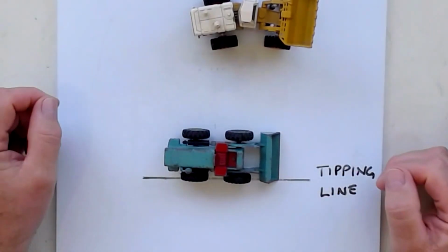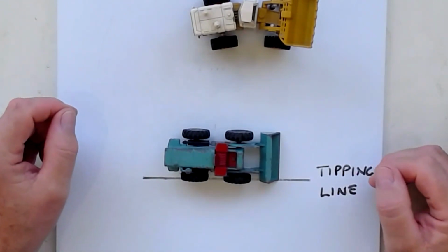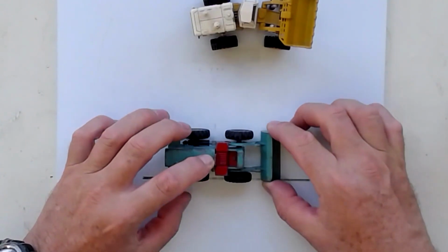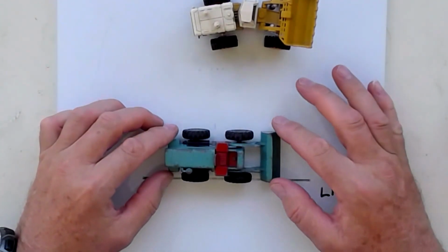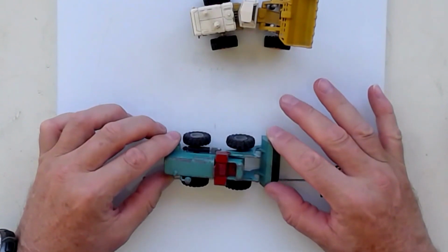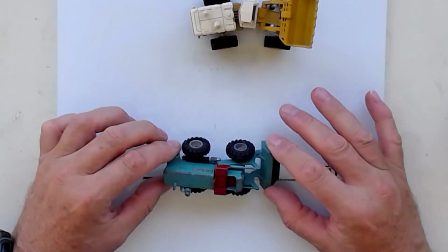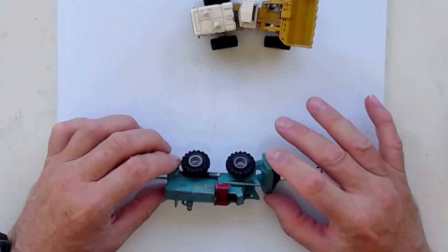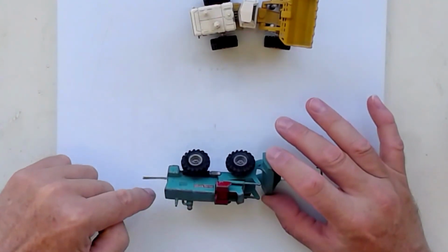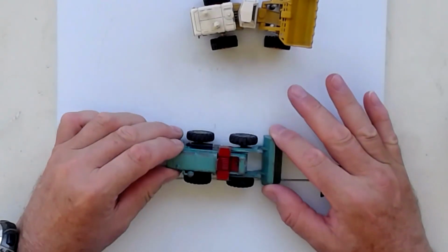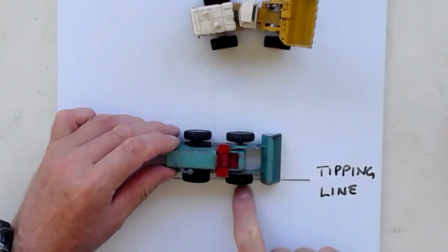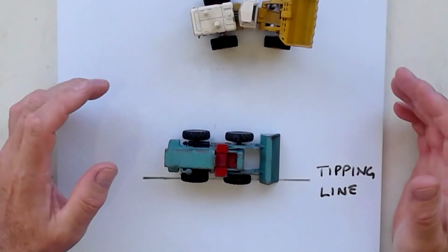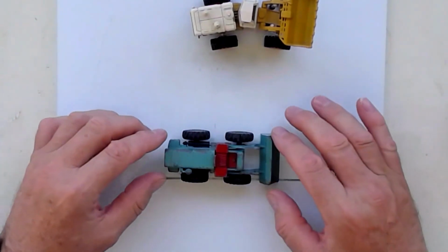When we look at a rigid frame vehicle, we can learn a few things. We talk about keeping the load close to the ground so that it can handle quite a lot of side slope before its center of gravity is on the wrong side of the tipping line. The tipping line is the outer edge of the tyre contact patch, the line about which it will roll over.